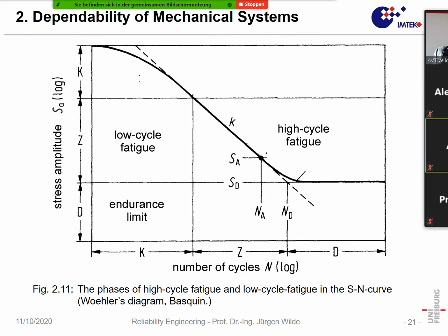Again, here we see the SN curve or Basquin's curve again. So again, that is important. That also could be a question in the exam. What would be the SN curve of a steel? And here you could say that is relatively easy to construct. We can say here typically the boundary is half a cycle. So that means when we just pull the part,